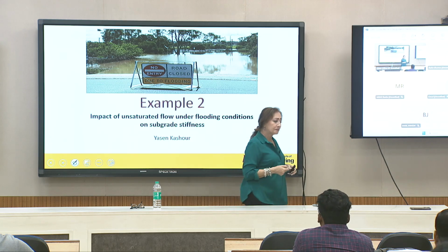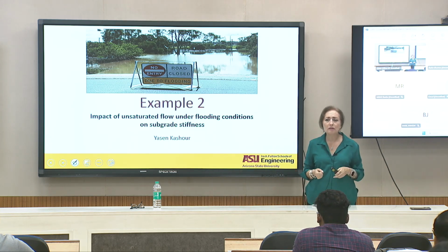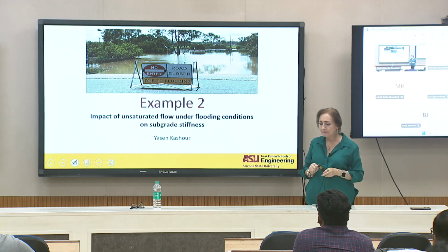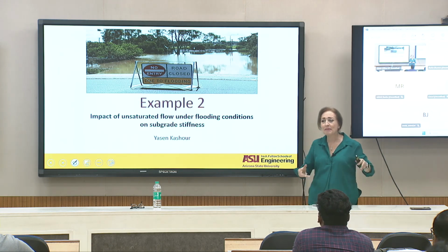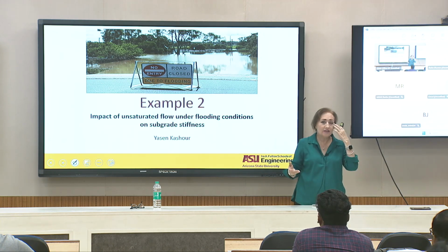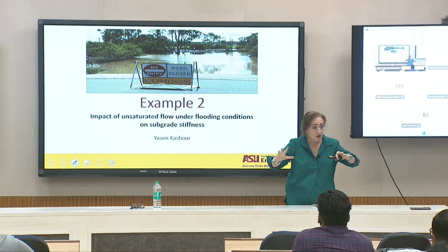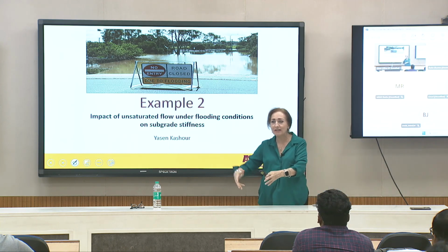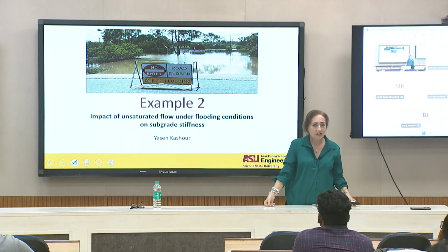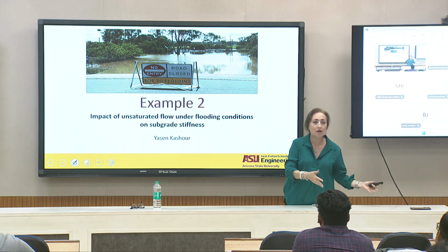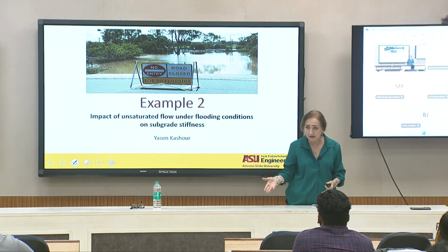But the problem is, they don't know when to open the road again after a flooding condition. They just wait for the water to subside or run off. Then they go with big machinery over there to take all the debris out. And guess what? If there is not enough time for the water to get out of it, they're damaging the road with the big equipment they're putting there to get the debris out. Okay? So the flooding is not causing the big problem, it's their own equipment at the wrong time, right?